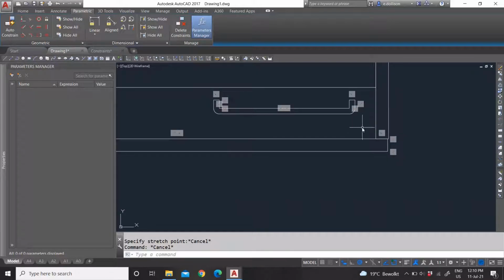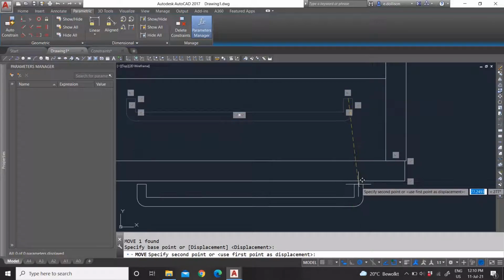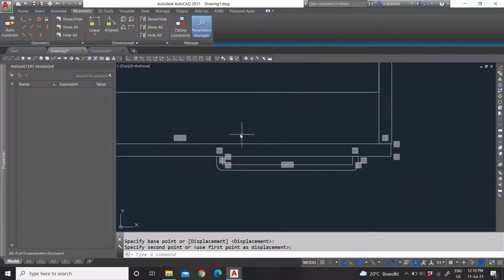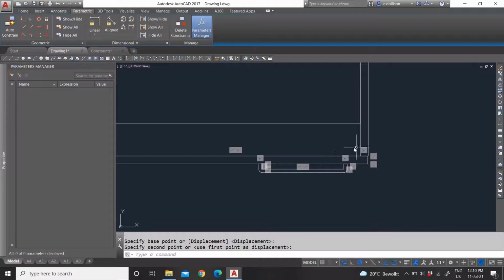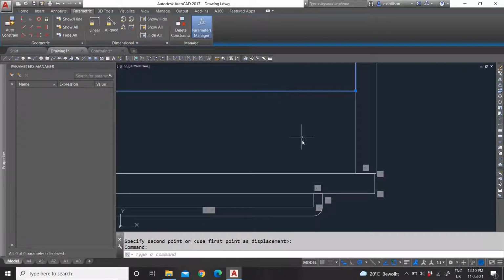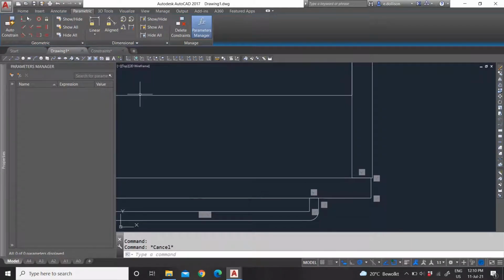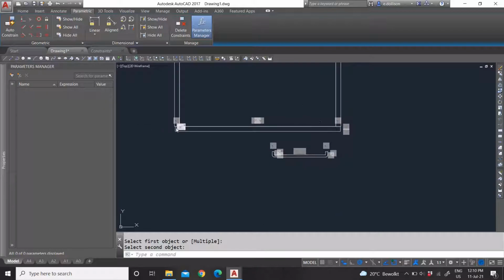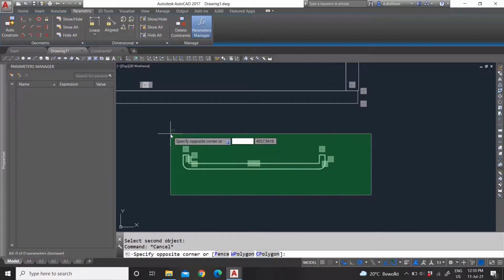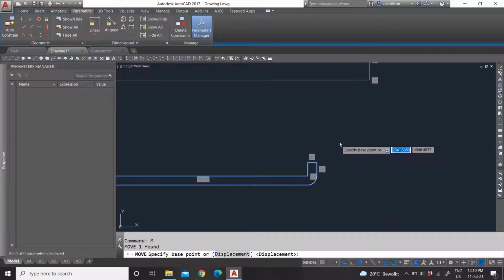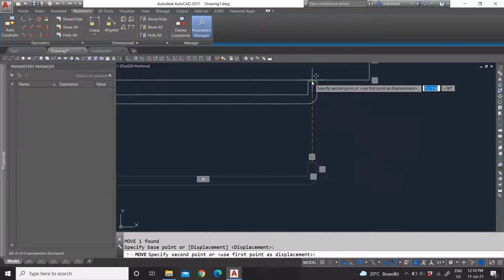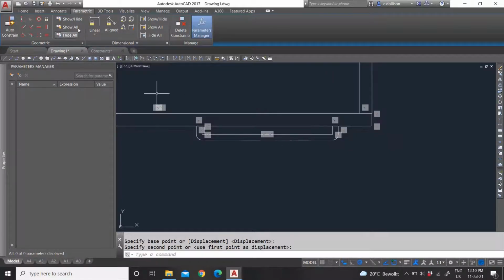So it's kind of difficult to set any distances with your geometric. So let us just move it for now. And now this line right here, which is the top of my cabinet, I would like it to be collinear with this line right here. So it would always be connected to that line. And as you can see, it did what it was supposed to do. It just joined each other. Let us move this one again manually.